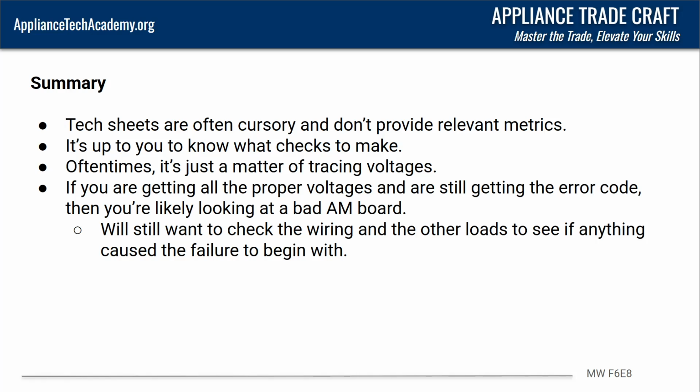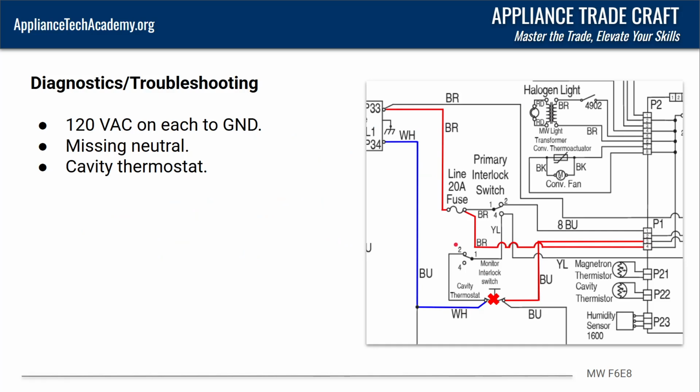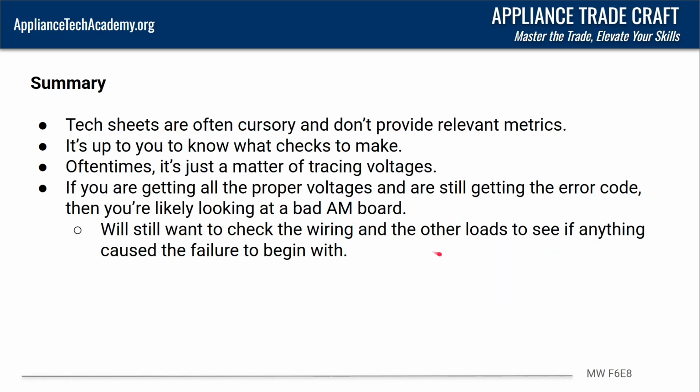But it's also to work to instill the basic diagnostic process with you. Because if we're just replacing parts left and right and not actually making checks, you're not doing your job right. You're going to look bad in front of the customer. You're going to look bad for your company if you replace a board and it's doing the same thing. Customers don't like that. They don't like to agree to a $300 repair just for you to say, oh, it turns out it's an $8 fuse.